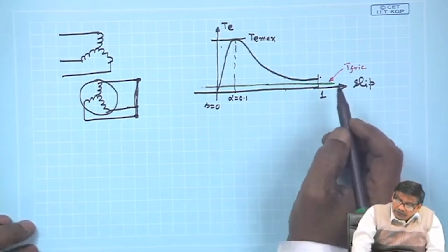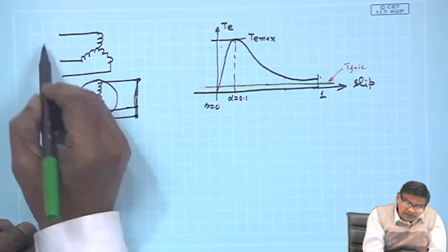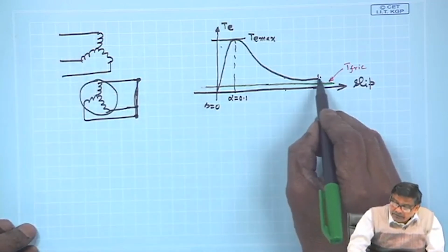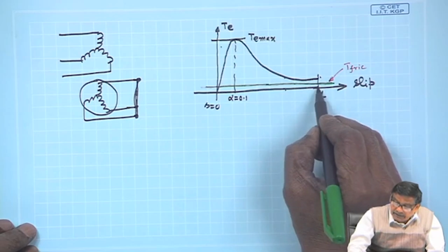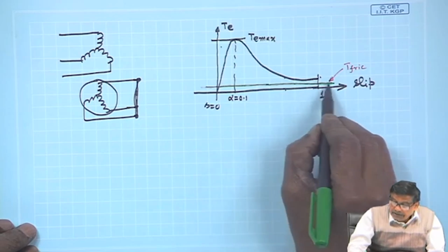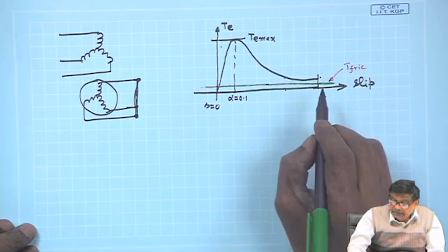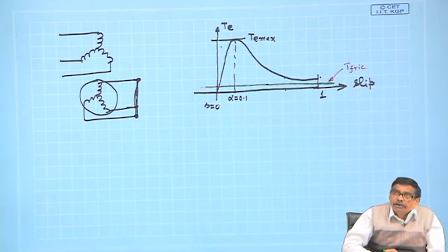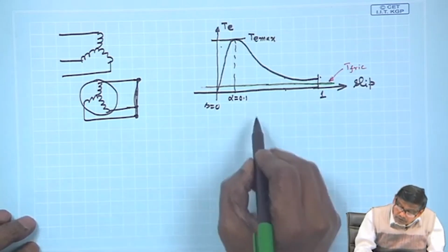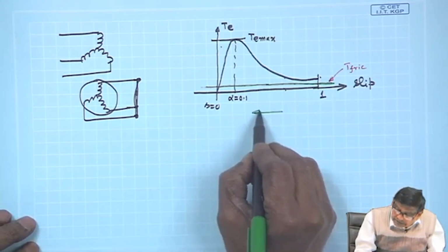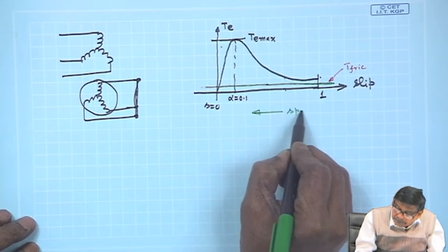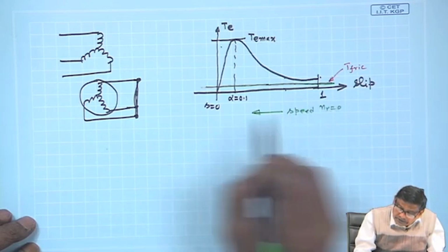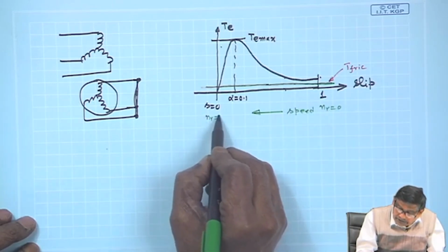Then what is going to happen when you switch on the supply? At that time slip was 1 and we say that this is the starting torque and opposing torque is this much. So, T starting is greater than T friction. So, machine will accelerate, and also do not forget that this side is speed. Always draw these two things to avoid any confusion. This is n r equal to 0 and this is n r equal to n s.